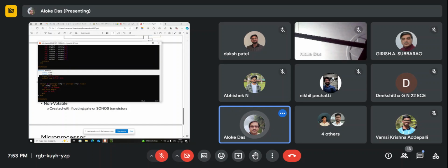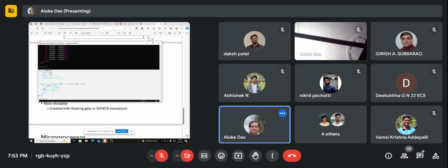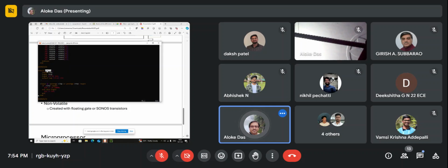See this module. This is basically a reg Q[15:0], meaning a 16-bit register, with a simple always block. This is one row of a memory, and the module name is memrow.